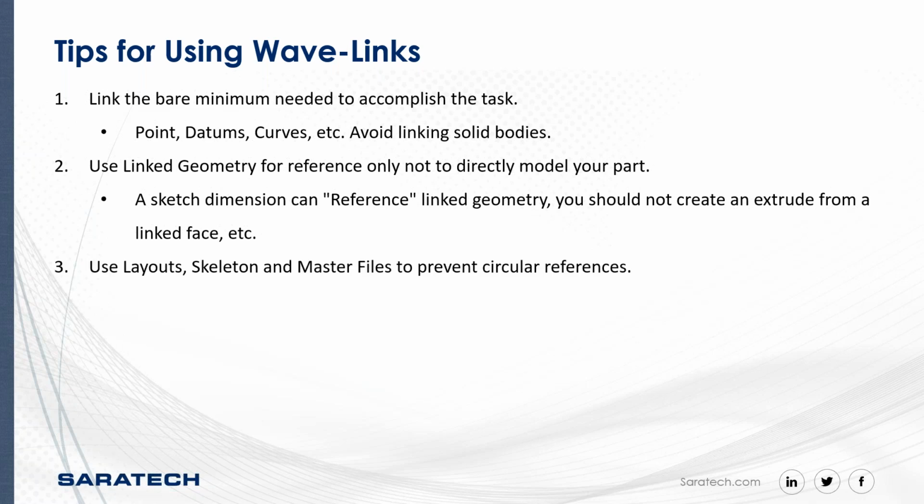Use layouts, skeletons, and master files to prevent circular references. It can start looking like a spider web. It'd be difficult to track if you don't have a methodology, a product structure in place from the get-go at the beginning for your team to grab those requirements. Worst case scenario is you're working with outdated interfaces, circular references, and then you have a bunch of warnings or error messages in your model tree.